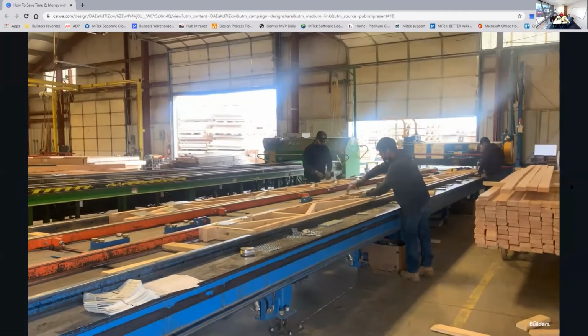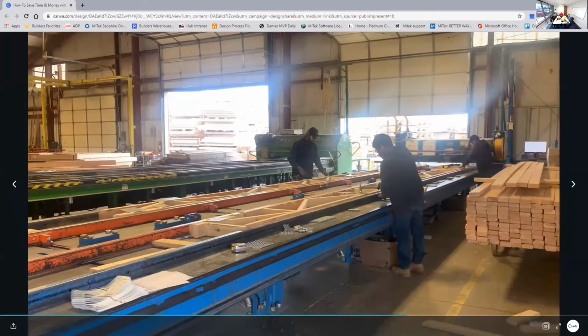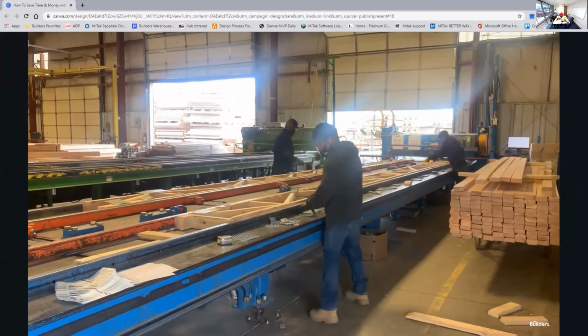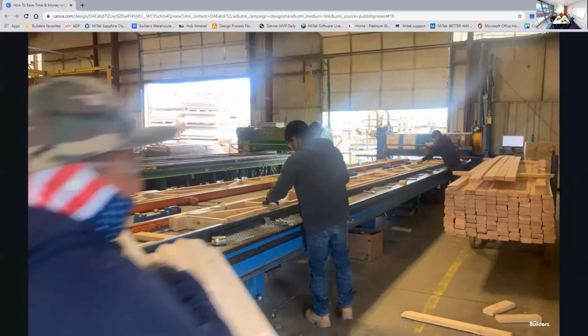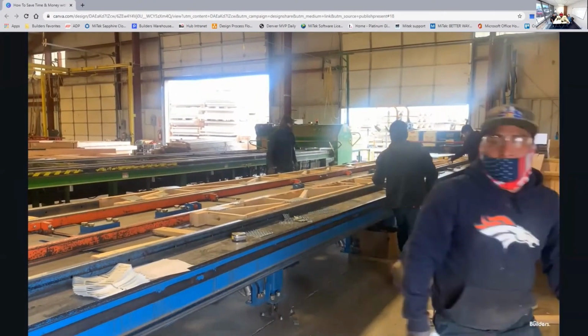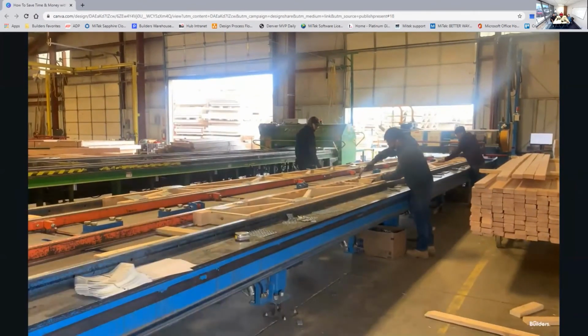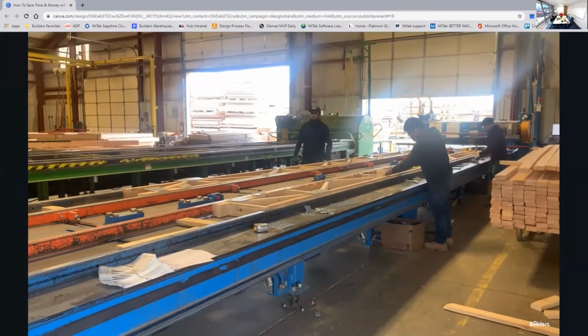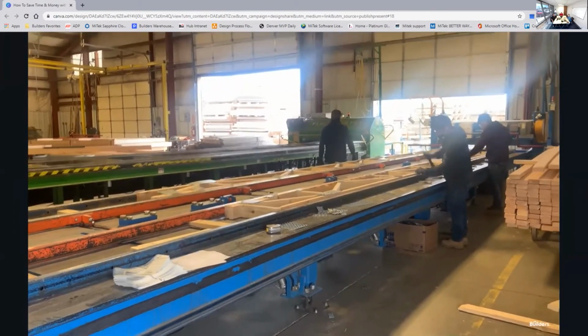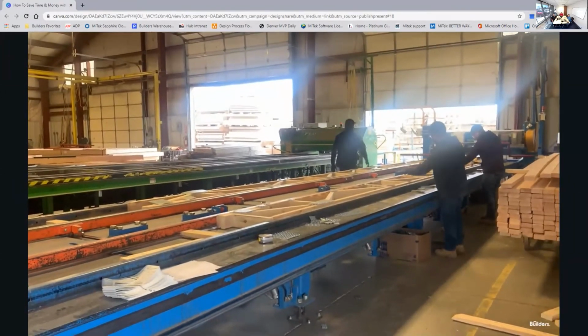The only difference in the application is that it's very similar in the way that we build them. However, floors, open webs are built upright instead of laying flat. And what this machine does is they'll build one side and then it flips the floor to the other side. One goes out the building and then it flips the floor to the other side and they start the next one. So they back plate it, so the connector plates are the same on both sides.